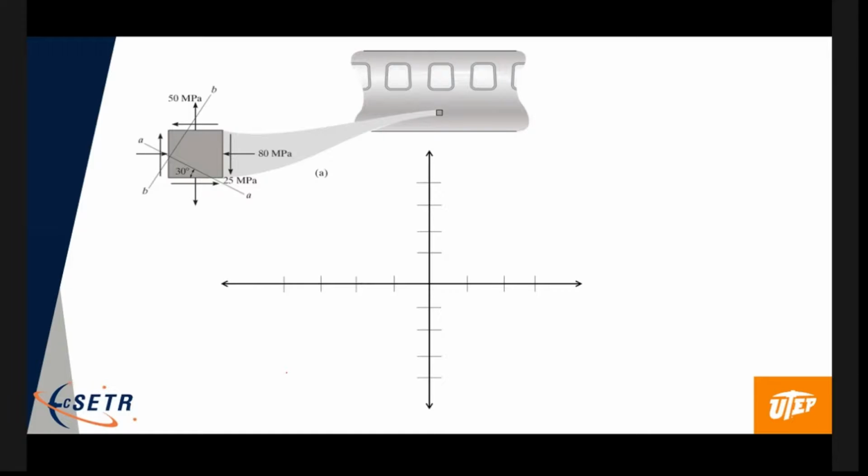All right. So let's look at our same example here, 9-1, and let's do it with Mohr's circle. Okay? All right. So here's our state of stress. So here is the first face, okay? On that face, right? What shows up here? Oh, okay, nothing shows up. All right, good. On this face, we have the normal stresses. And then on this axis, we're going to have the shear stresses where clockwise rotation is up and counterclockwise is negative.